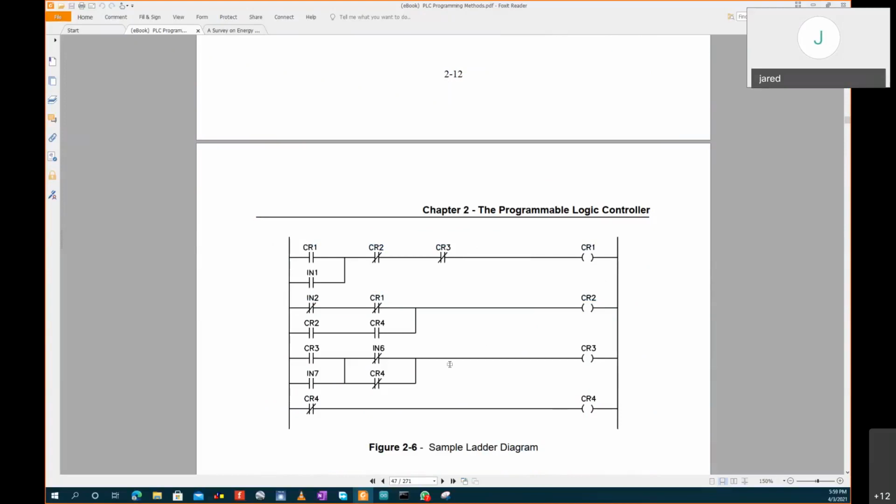Now this is a full PLC in action. So you have your circuit here and you understand what this means. It's normally closed, normally open, normally closed. You can see all these combinations. There can be a lot of matrix. You need to have Boolean logic. Maybe you have those logic circuits, so you want to do some computation with the AND gate, the OR gate. This is where it comes in very useful, because if you have 100 inputs and you don't know what will happen, you have to analyze them slowly and then see how you're going to implement them in the PLC.